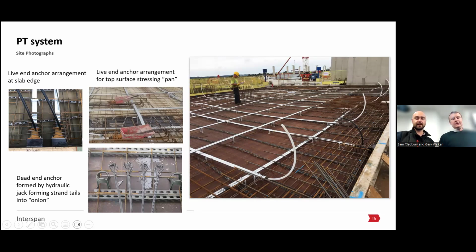So we've got some edge reinforcement, some U-bars and lacers. We've got some mesh in the bottom for anti-spalling, which comes out of the Eurocode. And our tendons are chaired and profiled on plastic chairs that are bespoke made, so we can support the tendon at 1 meter centers to achieve the profile that we've designed to. And then around the top of the column locations, there's punching shear reinforcement, which can either be bent links and bars, or it can be bars with shear studs or rails, proprietary rails.